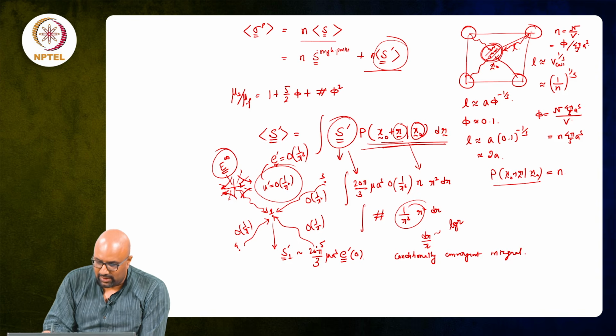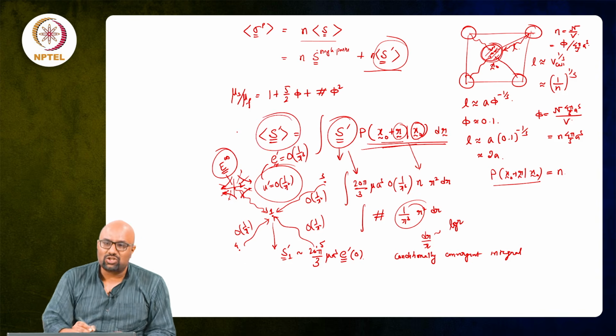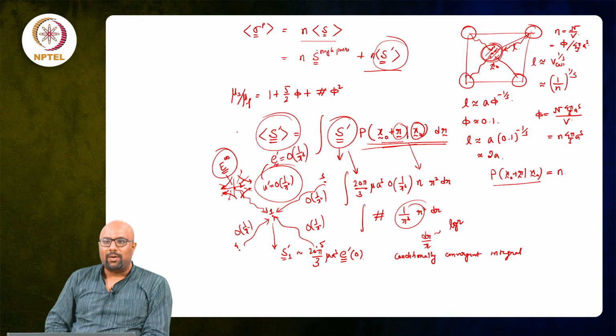So, we are stuck in a place where we do not know exactly how to find the next correction to the viscosity, because we are getting this kind of a complication where we cannot compute the average contribution to the stresslet due to two particle interaction.